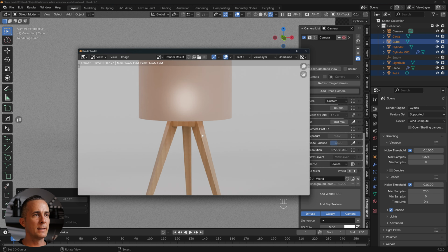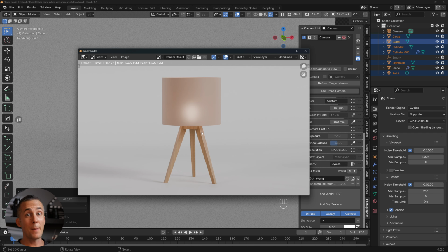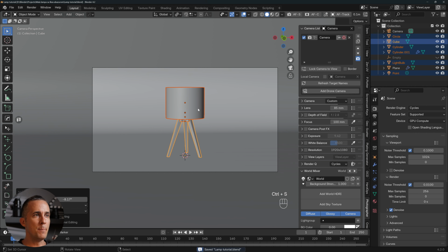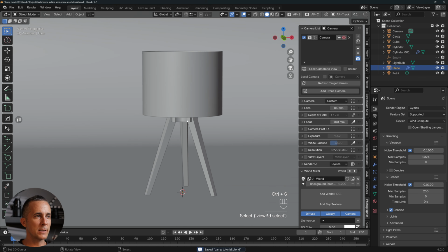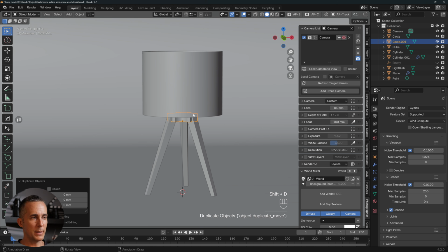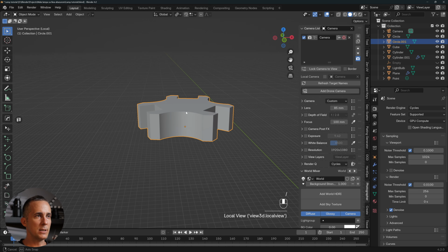Okay, this is perfect. I have really cool reference for my lamp. And now how I will make this in real life. This is really cool trick. So what I want to do here, let me show you really quickly. I will go back here. And basically I want to use first of all this segment right there. Let's make a copy. Shift D, okay. I will press escape. I will go and move it on X-axis somewhere here. And I will just isolate it to see only that one.